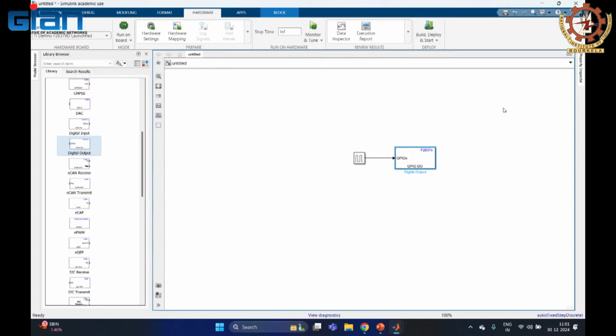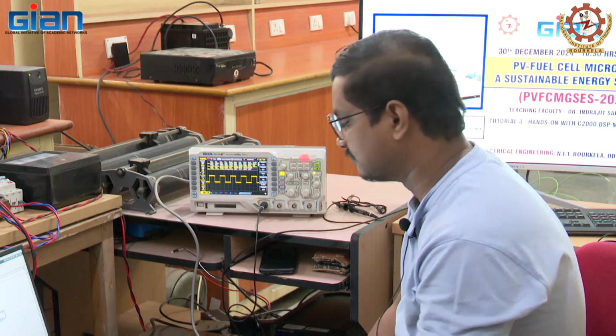As we can generate pulses from the GPIO pin, why do we need to go to EPWM? See, there is a limitation for GPIO pins also. There may be chances of missing the pulse at high switching frequency. So we require precise pulses. So we go for EPWMs.